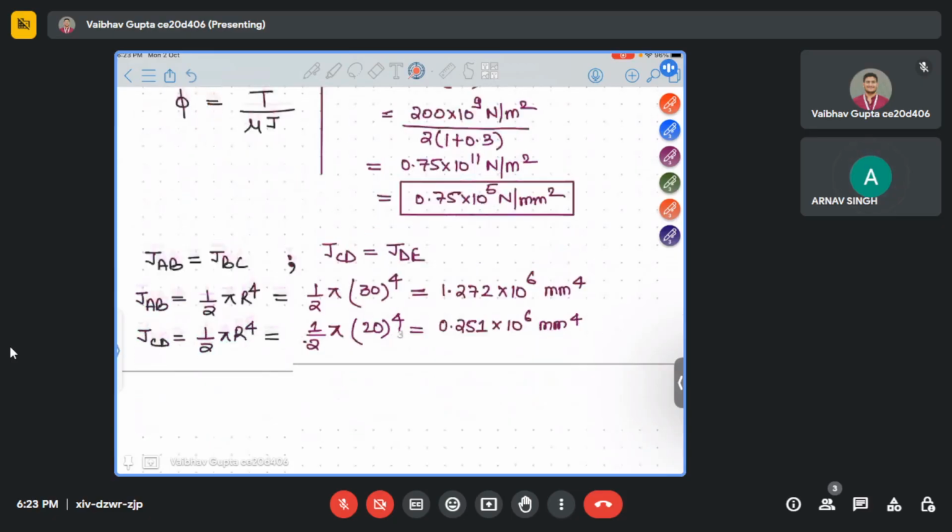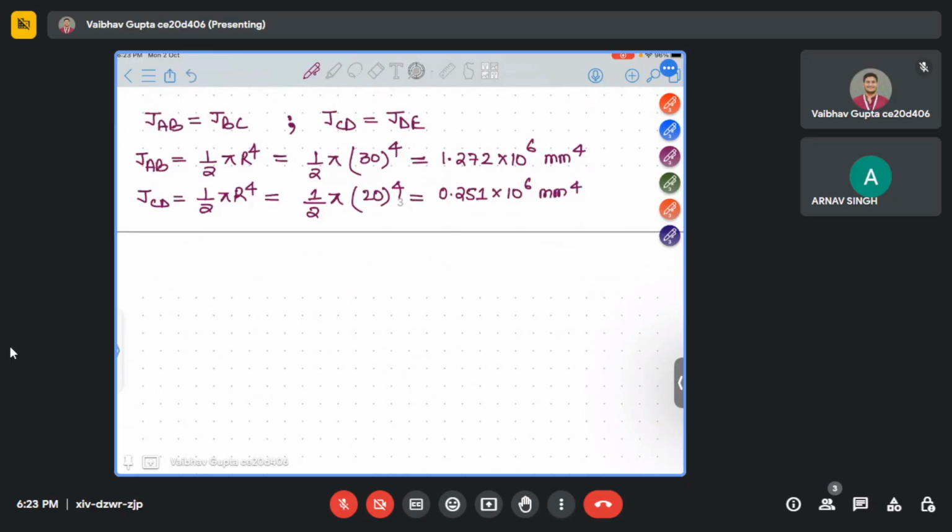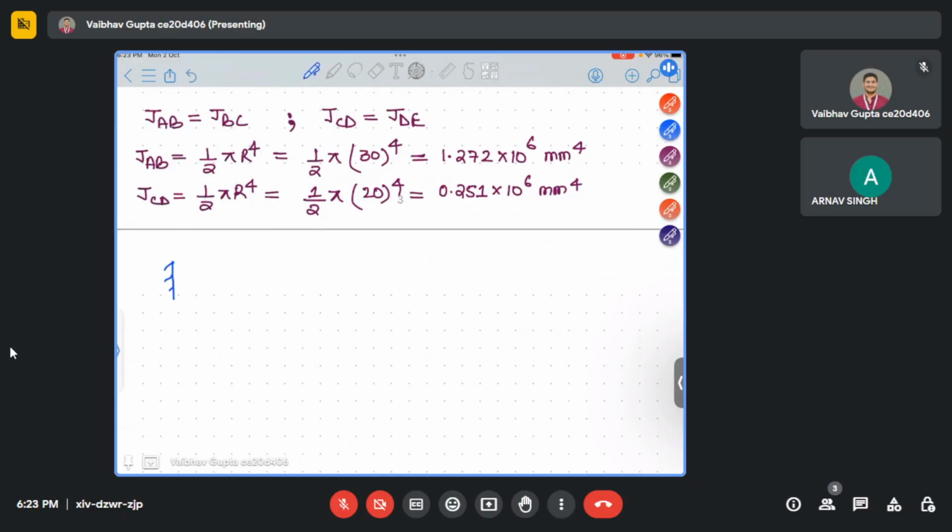Now I'll show you how to calculate phi. In the question we have given 5 different elements. Suppose I idealize this as a single line element, where we have A, B, C, D and E. They have asked what is the angle phi A. This angle will correspond to this angle also, and this angle also, because at other points also we have the load supplied, torque is applied.